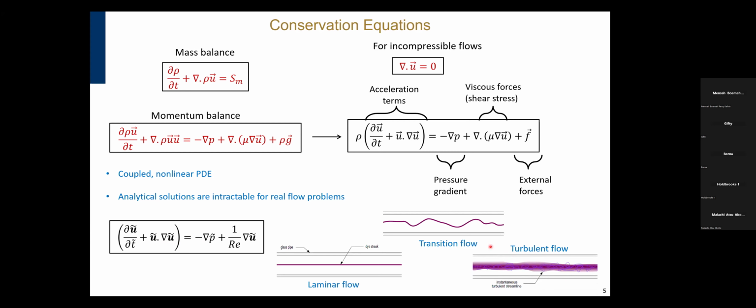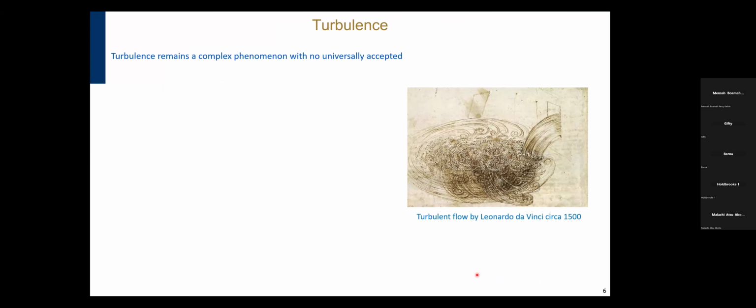Now, let's take a look at just the streamlines. Once you look at this flow in the turbulent regime, you see that you've enhanced mixing compared to laminar flow. This is really important for a lot of engineering applications, and it is what you would seek in the case of a heat exchanger and all of the processes that we handle in chemical engineering. You would want to get as much turbulent flow as possible. So this is something you need to take care of.